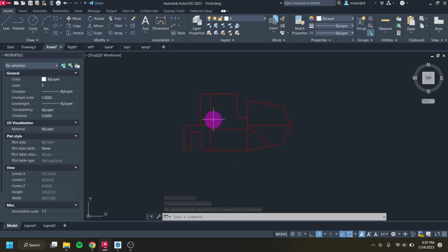After you do an overkill, it's always a good idea to look over your drawing and double check that everything there is in fact the line that you want to keep. If you do have different color lines, let's say I had some edges that I wanted etched and edges that I wanted cut, and when I had it ignore the color, it kept the blue line where I wanted a red line. Again, that's something you want to double check. So that's one way that you can have those overlapping lines removed and condense your file so you can print out using less material.